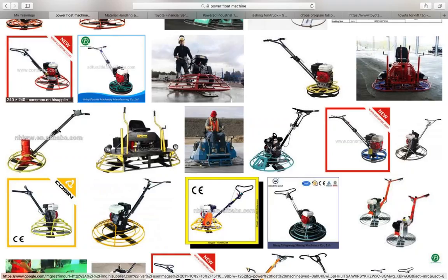Okay. And then some common causes, right, of form failure. This is a perfect example of concrete pouring forms and where they may fail. Look at the second picture again, and you'll see that they're basically pouring that form into place. And this is what's happening, right? Form ties may be incorrectly or improperly placed. Also, we may exceed the design pressure, so it may force that form to collapse as well.